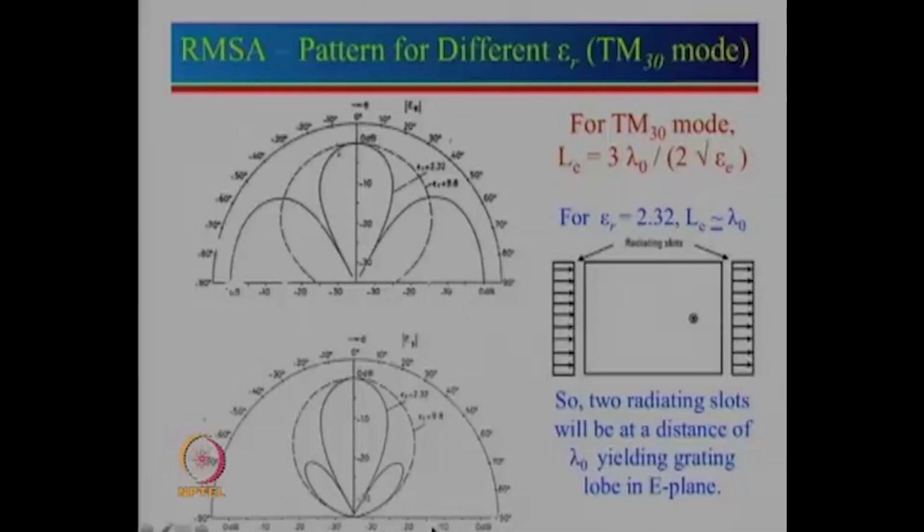Now, the similar thing you can see here, but here we see that there is no grating lobe coming into picture, and the reason why grating lobe is not coming into the picture here, we have to visualize along the H plane, where the slot element pattern actually has a 0 value. So, if that 0 value gets multiplied by the larger array factor value, 0 multiplied by any number is 0. So, that number is coming close to 0 here.